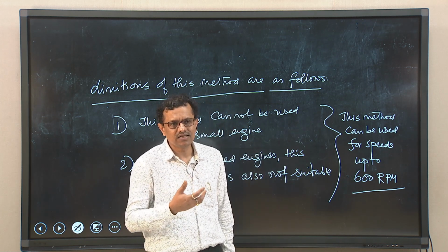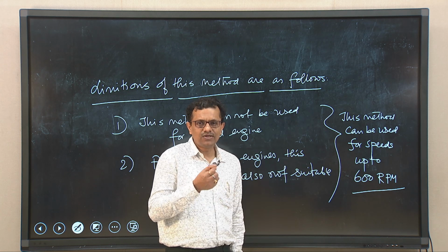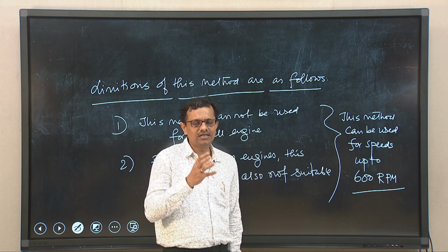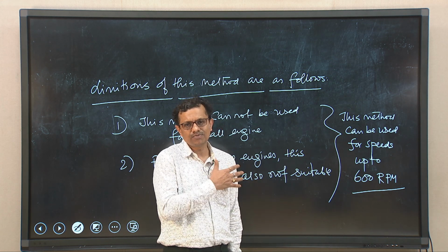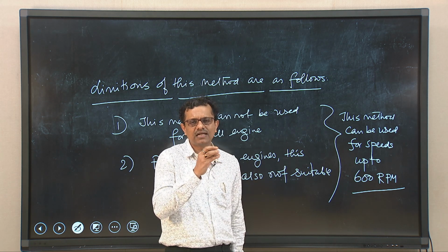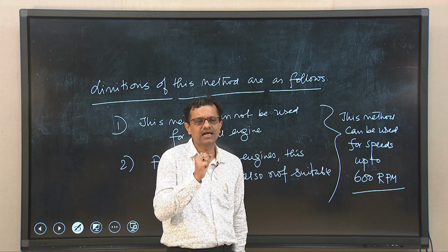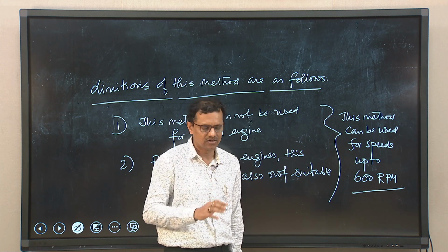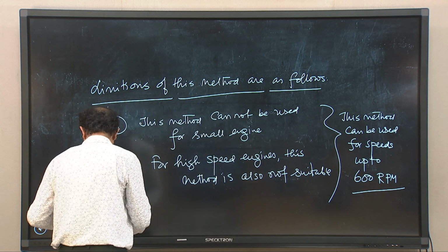So, in all these scenarios, if we need to know about engine condition or performance, this particular method is very suitable, because it will give some information at each and every stroke about the pressure inside the engine cylinder. Okay. So, that way it is suitable.